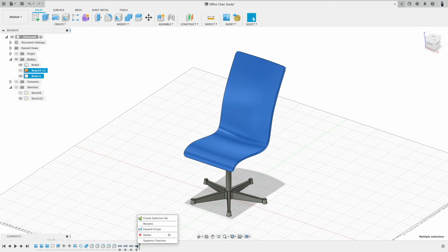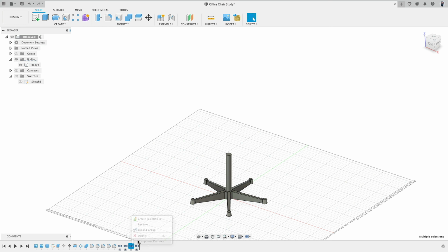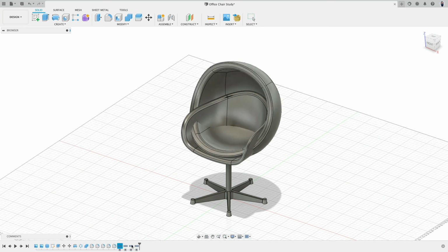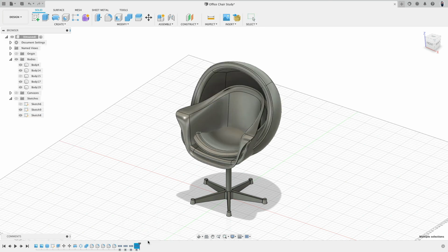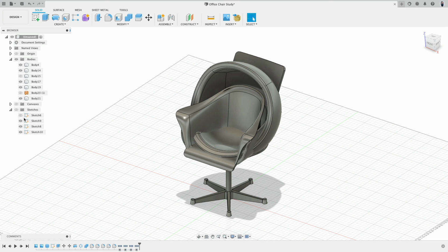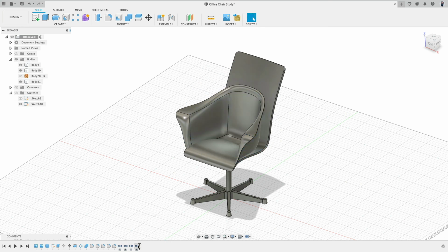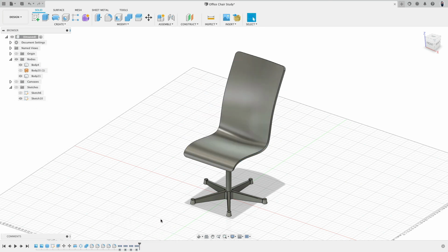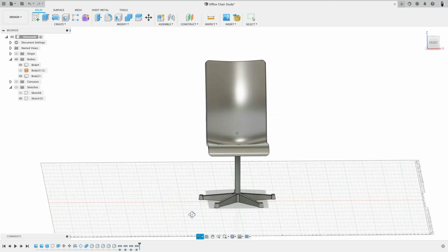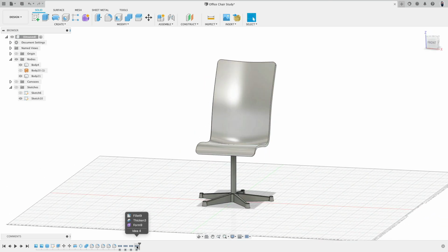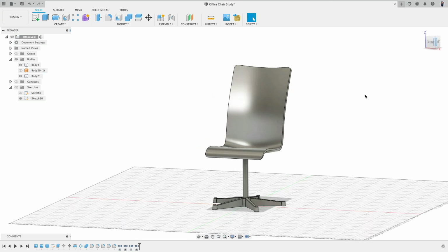Very nice. And then this whole idea here with suppress, as you can see, is just a tool if you want to park ideas. You do not have to hit suppress, but when you unsuppress them, you see everything here gets kind of filled. And I find actually that this suppress function is really quite useful when you explore variations in a more loosely approach, because then you can make a copy and then put everything into a group. Your timeline doesn't explode and you can organize your steps or your thoughts actually much better.